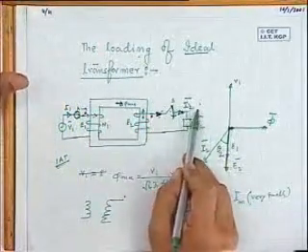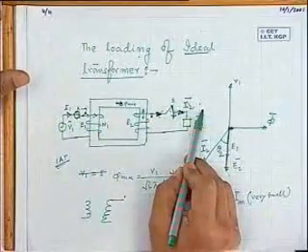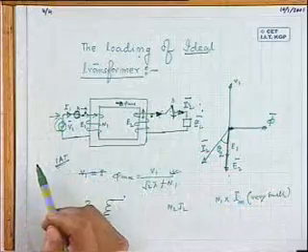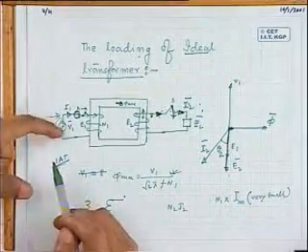You have connected a load on the secondary side, it delivers power. Forget about direction of flux, etc. Output power is there. But this is the only source of power, so it must now pump power into the primary. The moment you want to drop power out of the secondary, power will be automatically pumped in.